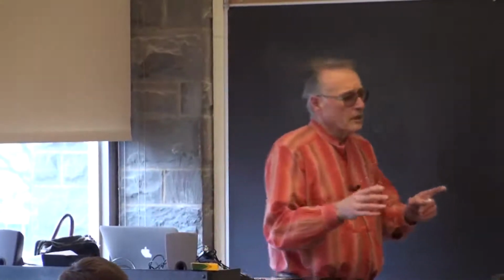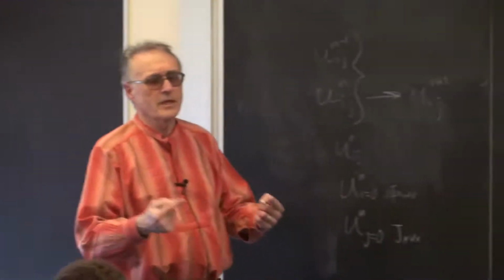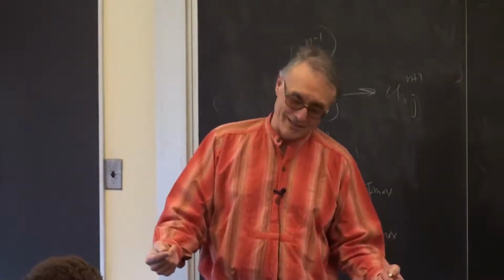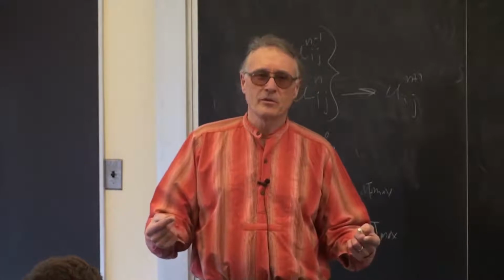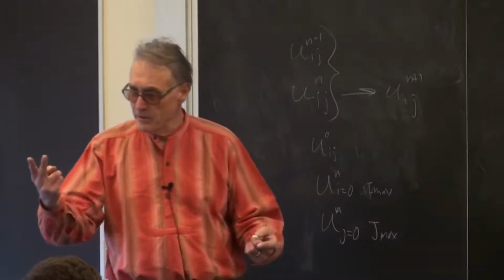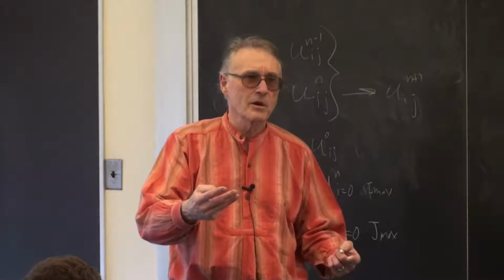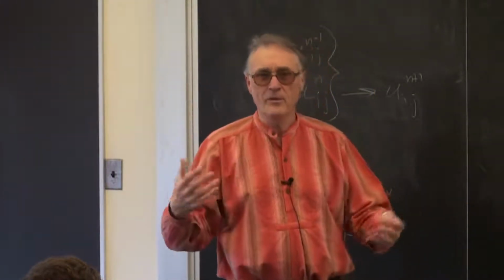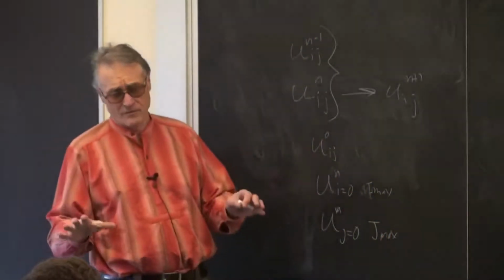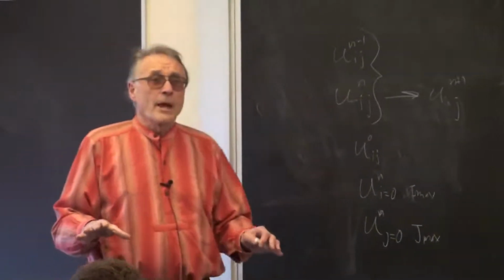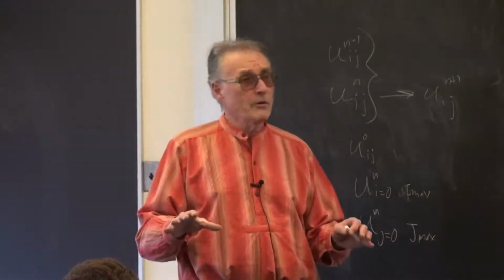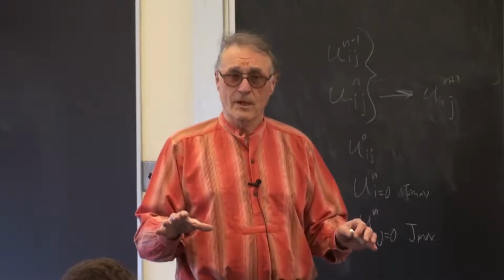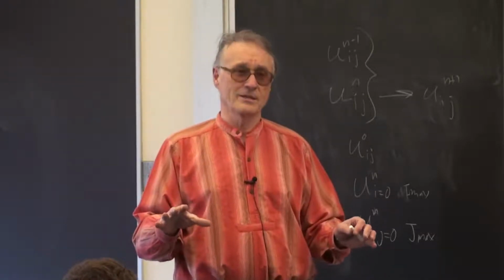Then I want to start talking about some of the physical aspects of the FPGA, because you're going to have to parallelize this code, and the way you do it is going to be dependent upon the amount of memory there is, the number of multipliers, the number of logic elements, the interconnects, a whole bunch of interrelated things that you want to optimize. So we have to talk about the physical structure. And once you do that, you have to say, okay, how in the world are you going to simulate the physical structure? And there's at least two ways, maybe three ways of doing that.